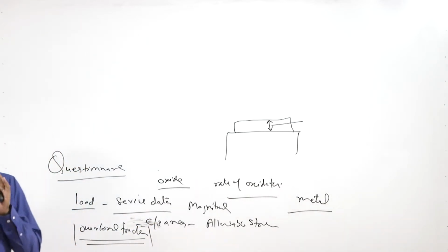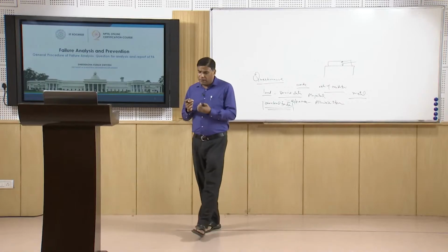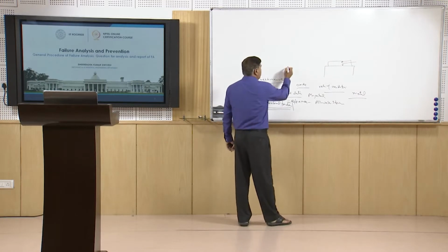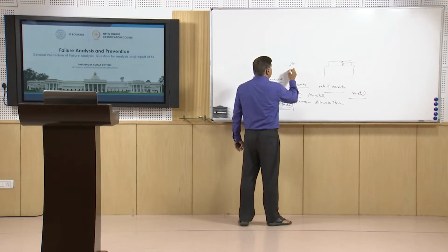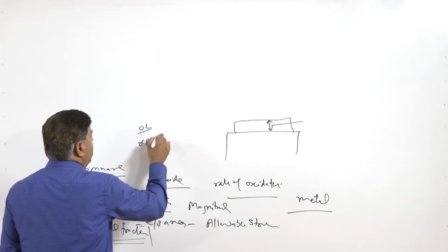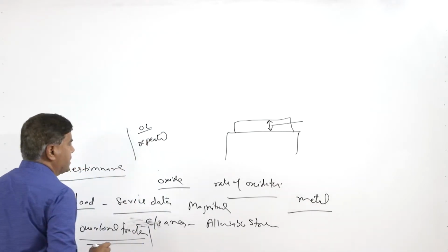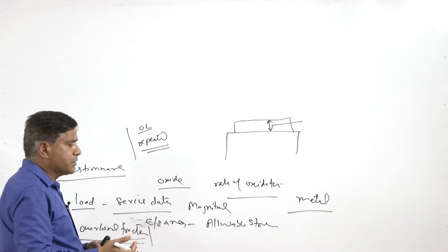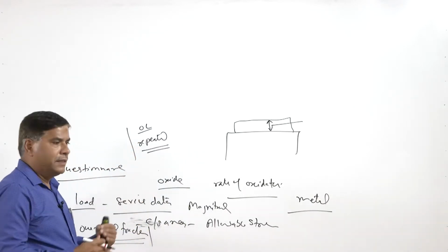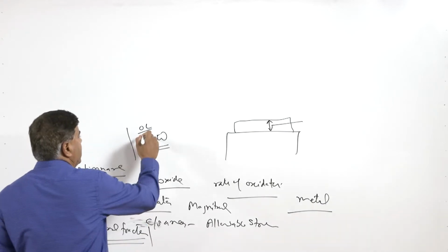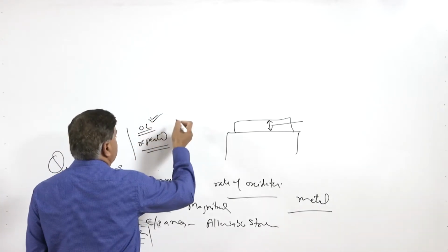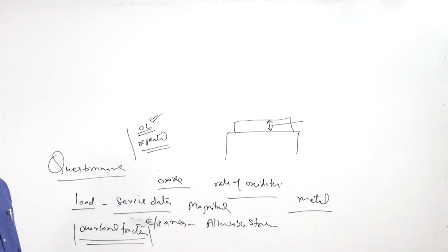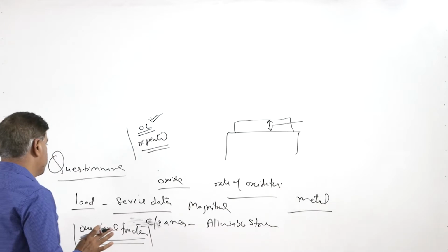So, intensity of the load can be understood in two ways. One is whether there has been overloading or repeated loading under which the fracture has taken place. Under repeated loading conditions, the load magnitude will be lower than the yield strength of the material, and in overload fracture the material will be subjected to stresses greater than the ultimate tensile strength of the material.